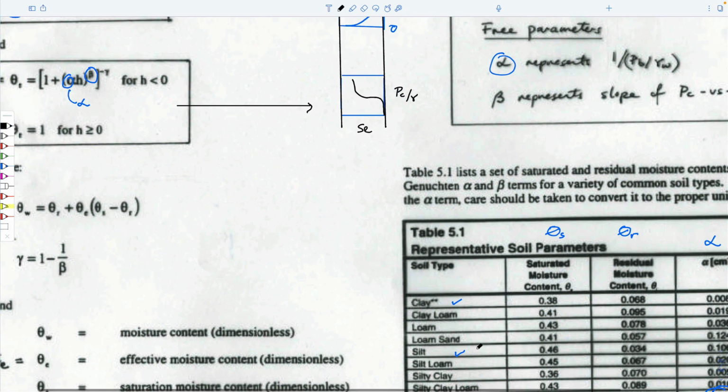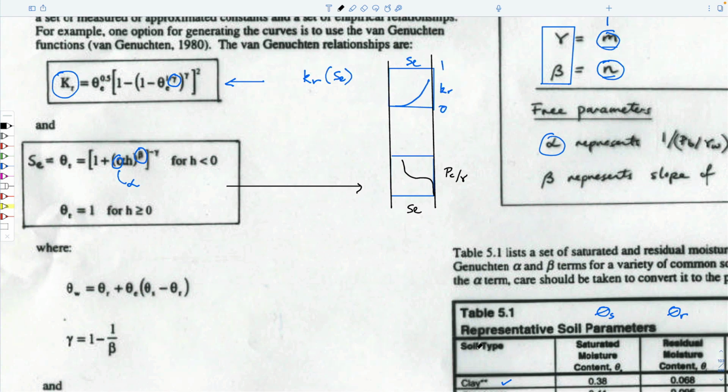That's it. And so instead of using very simple capillary tube models, which are binary, to reconstruct the behaviors of these systems, we can get the real deal, which represents, at least for the wetting phase, the relative permeability and the capillary pressure in what we'd call drainage, I guess. And we can reconstruct these curves for these media.